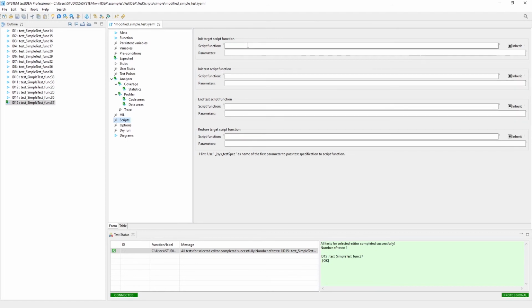So if you need any kind of special initialization, for example, we had a customer that was running some kind of EEPROM failure tests, and they were using this functionality to download EEPROM error data and then running the test with that different error data loaded to the EEPROMs. With the Python scripting, you can access all the functionality of the debugger. The scripts allow you to basically access everything that you can do in the tool manually.